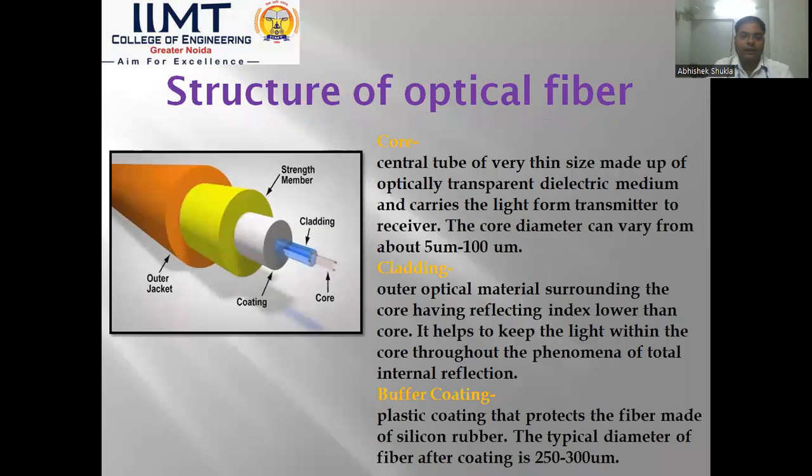Now, look-alike means how the structure looks. You can see from the picture, in the structure of optical fiber, in the middle the core is defined, and at the outer end the cladding. The core is where our light signal is transmitted. The cladding has a change in refractive index and is coated above the core.